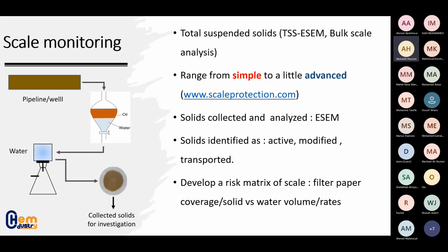Then they will tell you if the solids there are actively forming, transporting, or modified. This will tell you, especially if you're doing a treatment like injecting a scale inhibitor, if the solids are actively forming, that means your treatment is not working. But if they are modified, that means the scale inhibitor is actually working well, and so on.